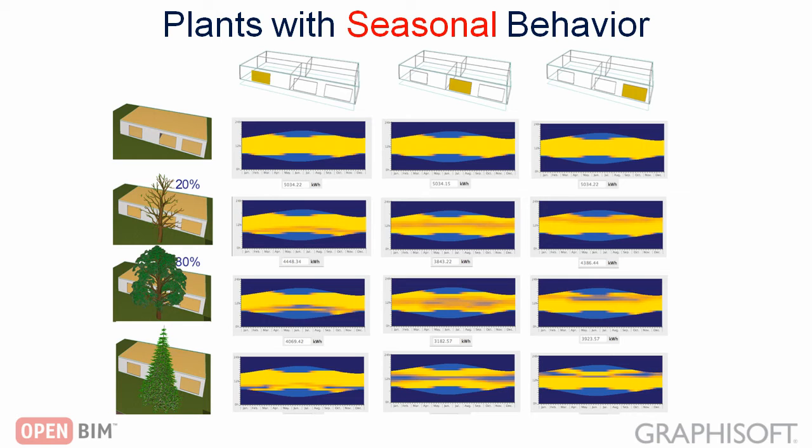building. It's visible on the solar irradiation charts that deciduous trees with denser crowns, more leaves, cast larger shadows on the openings throughout the year. Additionally, deciduous trees' crown densities change with the seasons, therefore they shade windows more effectively in the summer, although they lose their leaves in the winter and therefore provide less shading. Less shading allows more heat gain through the transparent surfaces in the cold seasons.